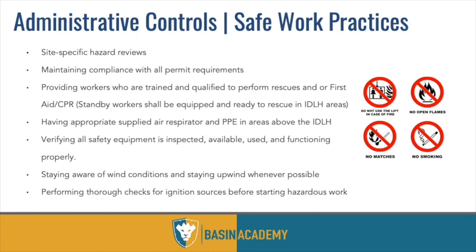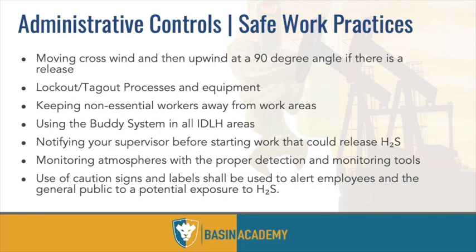And then as well as inspecting your equipment, making sure people are standing upwind at all times, no matter what, even if they are under air. Prevent the exposure as best as you can all the time. So safe work practices, again, communicating with people, having a buddy out there. These would all be safe work practices. Like, hey, I'm going to drive into this area where we know has H2S. If I don't call you in 15 minutes, send somebody. There are gas monitors that, if you fall over on your side and are inactive for so long, will send out a signal and people will come for you. There are a lot of unique administrative controls out there, but again, these are good planning tools. The best thing we can do is get rid of it completely. If not, then we need to make sure we have very strong administrative controls in place.